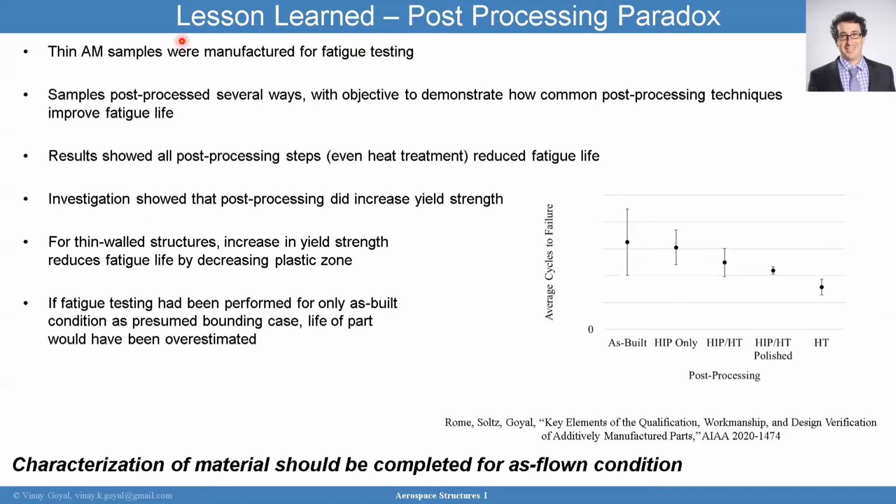So to summarize, Dr. Ron, see if I got it right. I think what I'm hearing you say is that when you produce results from a model, or you're trying to do a design and you have some strain gauge data, it is very tempting to go ahead and compare that to a single data point. And your point is it's stronger to show your prediction in light of the scatter in the data, because that shows you where, and it can even tell you why you're off in terms of scatter, right?